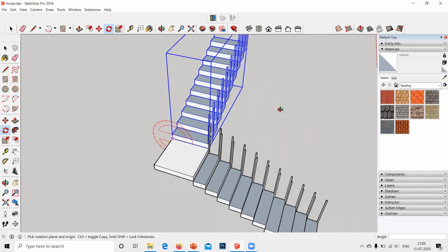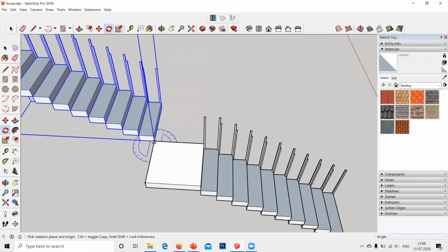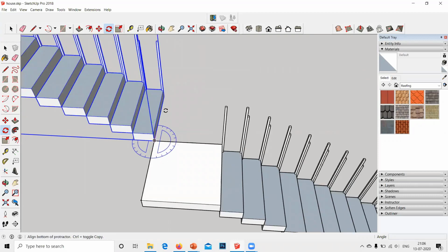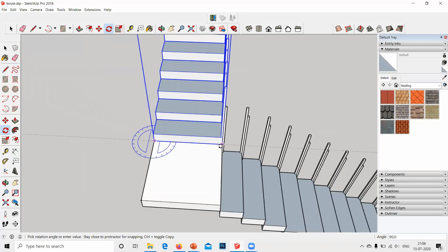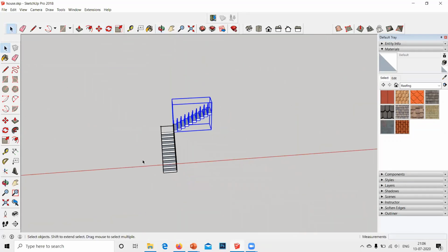Just like what we do for a door, we have to make the same only 3 clicks. I'll just undo and tell you. Click over here, selecting this. Okay, so I wanted to delete this portion of my stairs so that whenever someone enters, it doesn't bang your head. Click. 3 clicks. Use your guidelines to mark the whole thing.